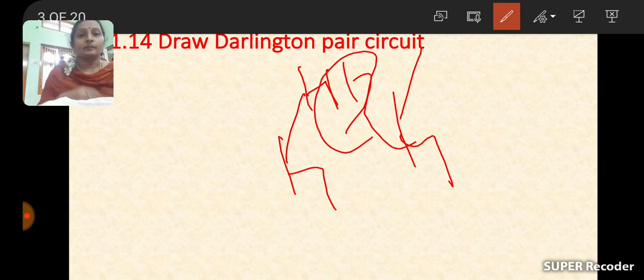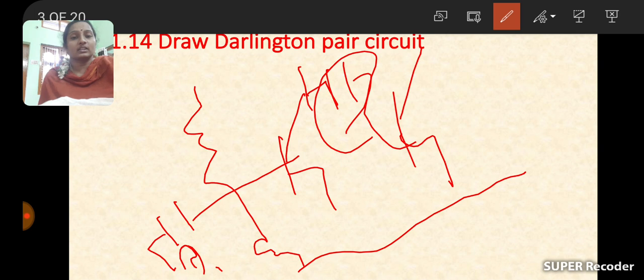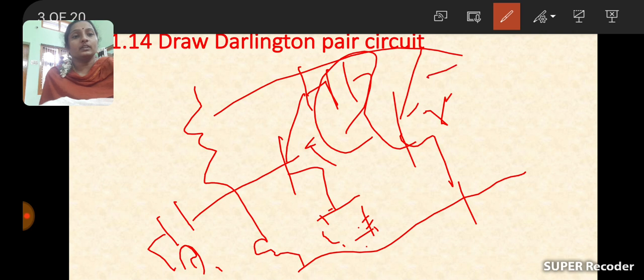In the construction of a two-stage RC coupled amplifier, there are two transistors, with resistors for biasing and stabilization, a capacitor Cin to allow only the AC input signal and block the DC, and the emitter bypass resistor and capacitor combination to provide a low reactance path to the amplified signal. This is the construction of our two-stage RC coupled amplifier.